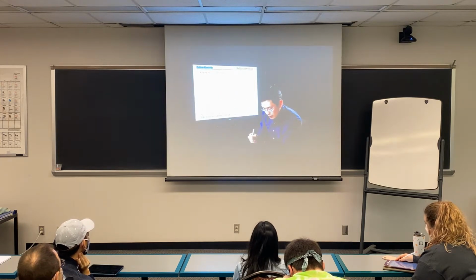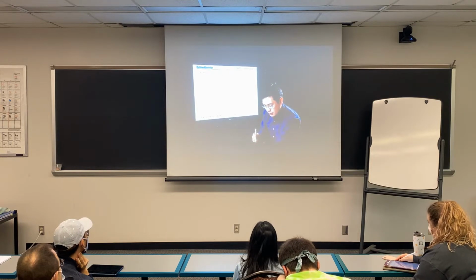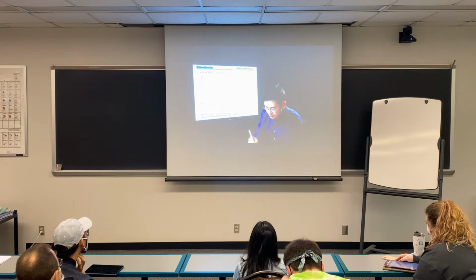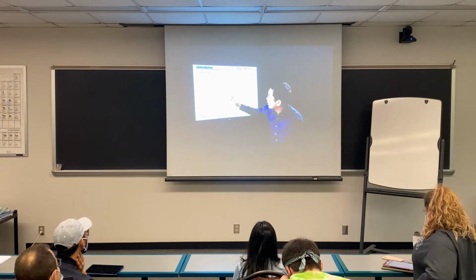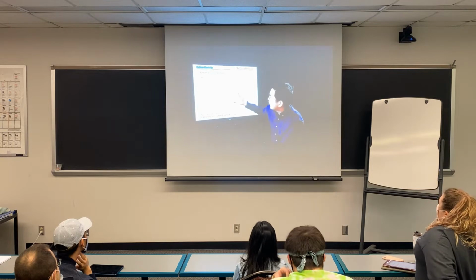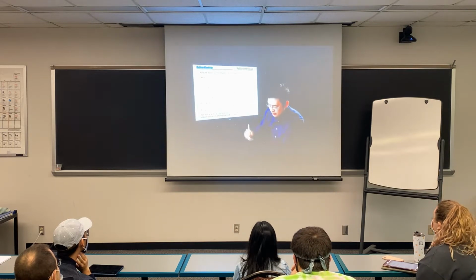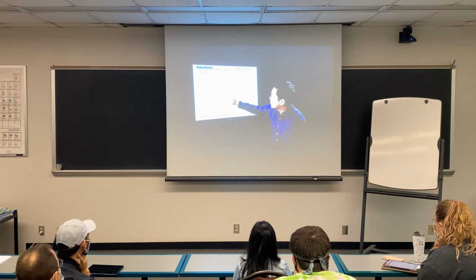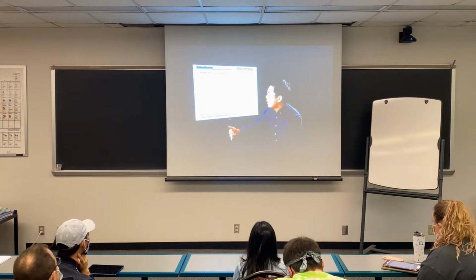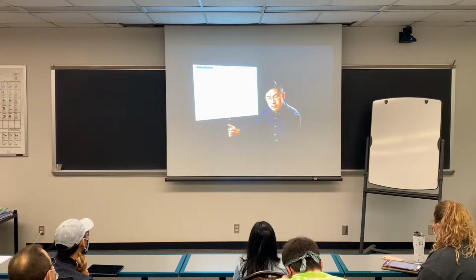Based on the continuum argument, Mooney added a second continuum term, C2, whose dependence on the extension ratio is weaker, depending on 1 divided by lambda cubed. By combining these two, we modify the original equation to have C1 and C2 terms. C1 and C2 are two constants, and you can get them from measurements.